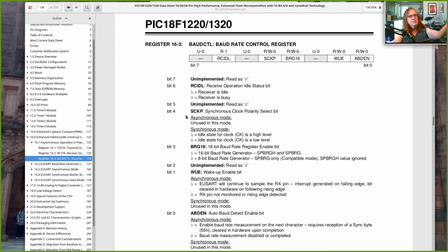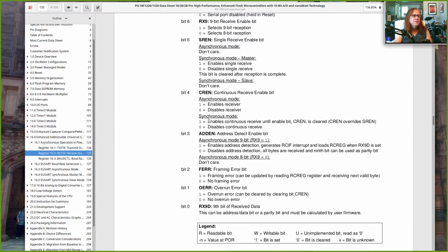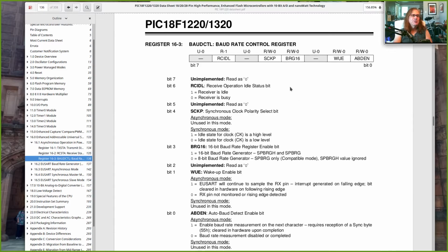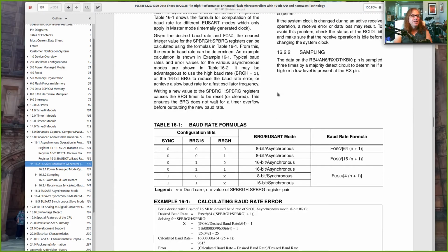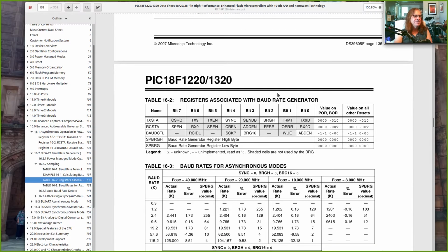So this is like all the other subsystems in the PIC. It's got a bunch of configuration registers and a register for setting up the baud rate, and protocols you have to go through to begin and terminate a communication. And it's also interrupt driven. You can set it up to say, hey, when you're finished sending a character, generate an interrupt so that I know you're ready to send a new character. Or when you receive a character, give me an interrupt.